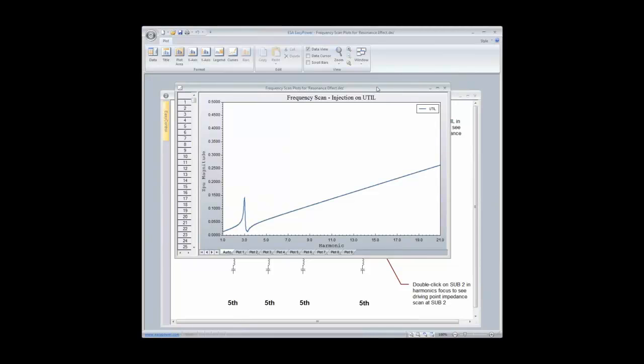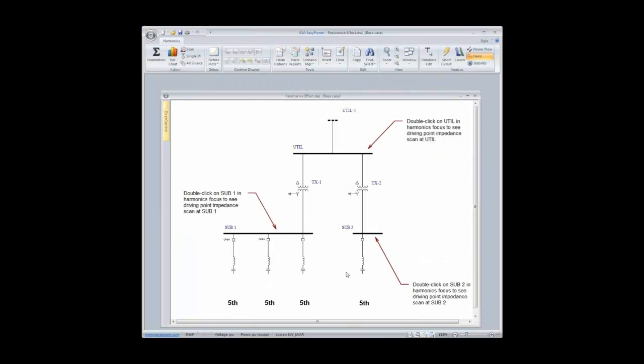And this brings up one of the key points that I want to drive home, and that is impedance buffering. If you're going to apply a notch filter of any form, you have to have some form of impedance buffering to isolate you from the rest of the system that you don't want to see your fifth harmonic filter. So in this case, I've got a utility grid up here, and who knows what might be up there? Who knows what type of distortion levels might be floating around?